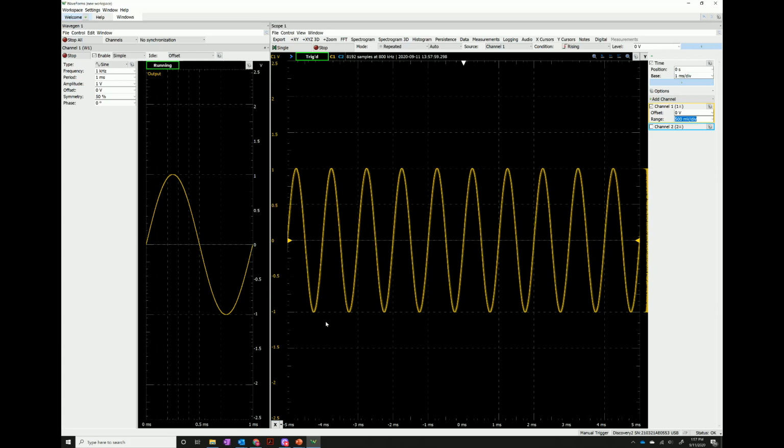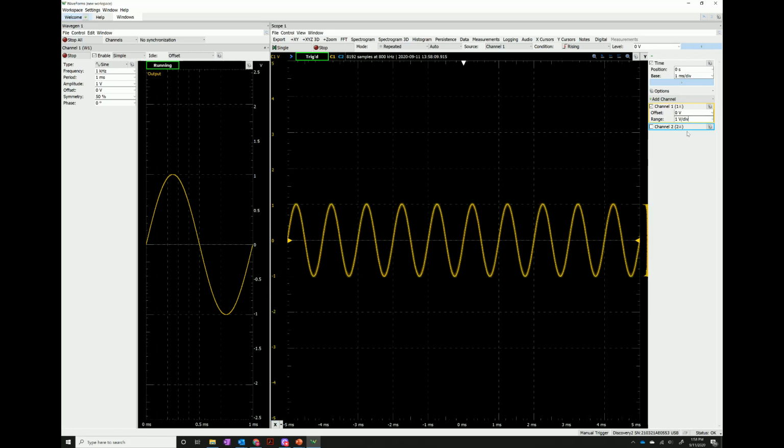Let's start here by observing what happens when we actually change the resolution of our scope. Right? Changing our scope's amplitude resolution for channel 1 to 1 volt per division, we can actually observe that this changes how the signal is viewed on the scope, but keep in mind that we still have an amplitude of 1 volt. Right? So now our peak is 1 volt, our minimum is -1 volt, and we still have the same signal, this sine wave with a 1 volt amplitude.